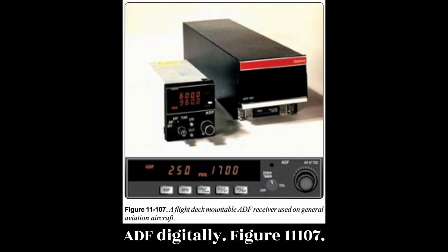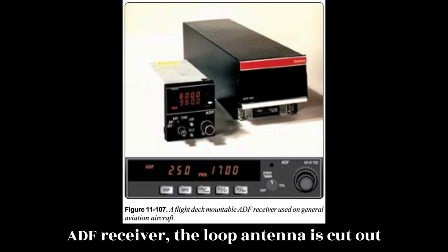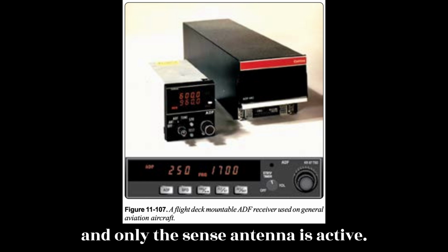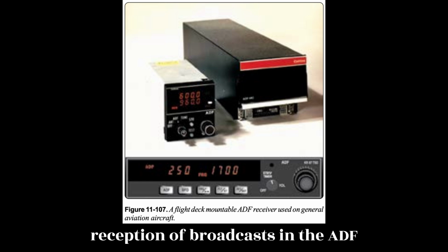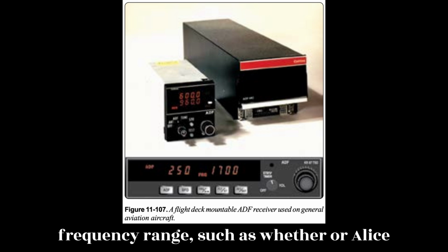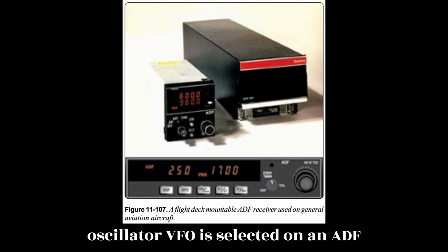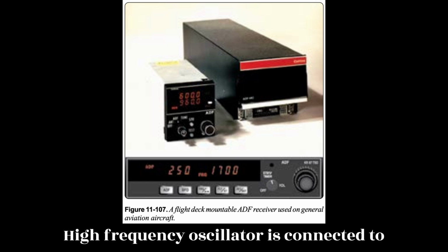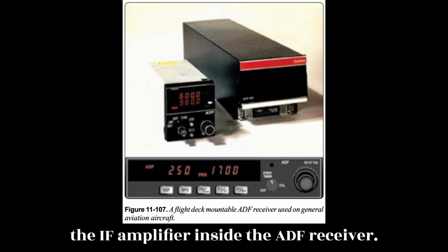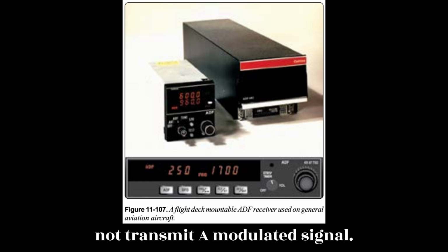Figure 11.107. When ANT is selected on an ADF receiver, the loop antenna is cut out and only the sense antenna is active. This provides better multi-directional reception of broadcasts in the ADF frequency range, such as weather or AWACS broadcasts. When the beat frequency oscillator, BFO, is selected on an ADF receiver/controller, an internal beat frequency oscillator is connected to the IF amplifier inside the ADF receiver. This is used when an NDB does not transmit a modulated signal.